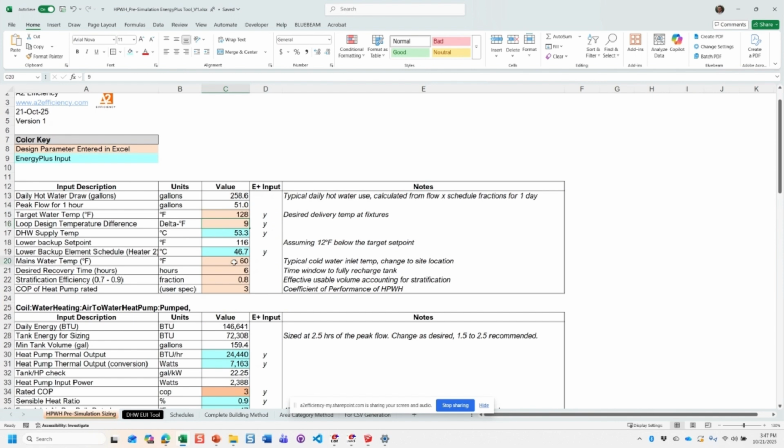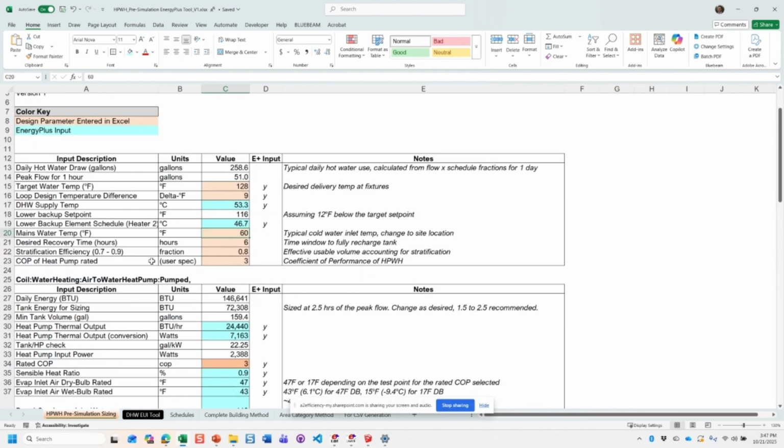You can then specify, and we're going to need it when we do sizing, a peak water temperature from the street. EnergyPlus actually has this as an input. What is the cold water? It changes each month. You're going to need a number. So if it's cold where you live and it's not 60 and it's 45, type that in. I'm going to pick 60 for now. It's going to be used when we size the compressor and everything else.